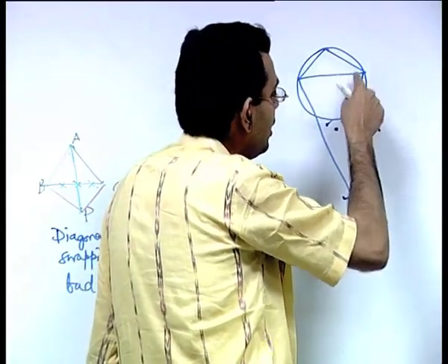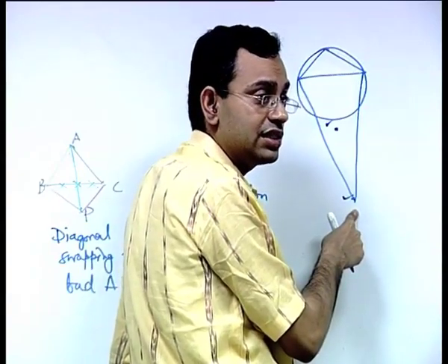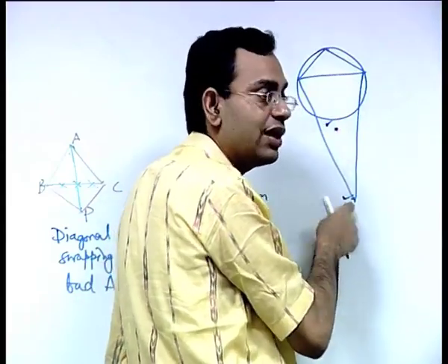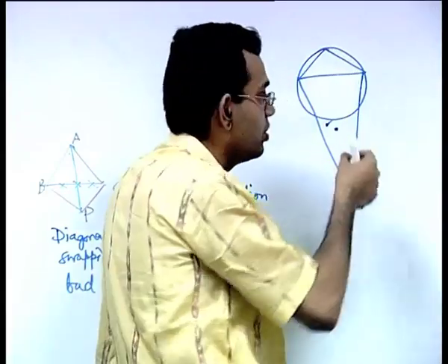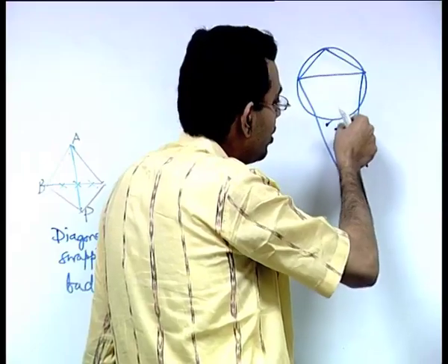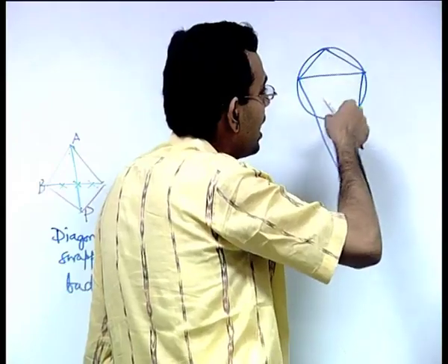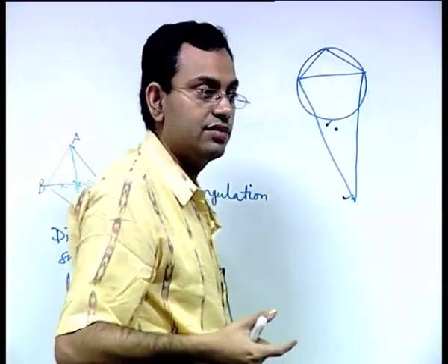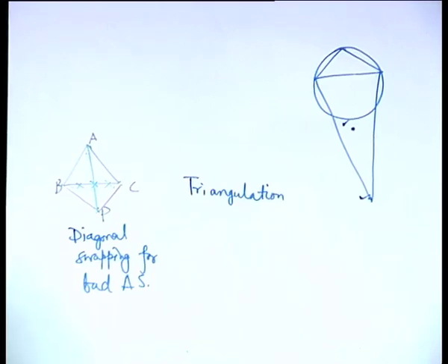You have a triangle, you just insert an arbitrary point, then make the circumcircle test. If the test is satisfied, it is fine, whether it is very close or very far away does not matter, because if refinement is required, you can always do that. So once this point is located outside the triangle, it is fine, and if it is inside, then you can make the diagonal swapping to make it alright. So either way, if it is outside, then straight away it is fine, and if it is not outside, the diagonal swapping will make it fine.